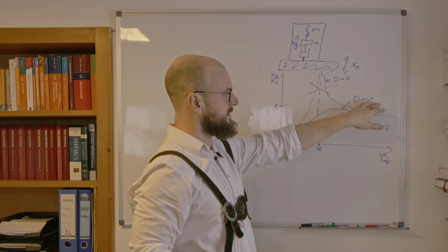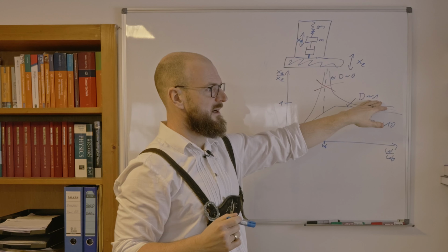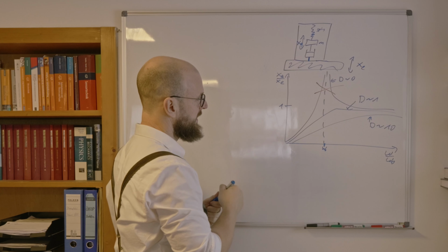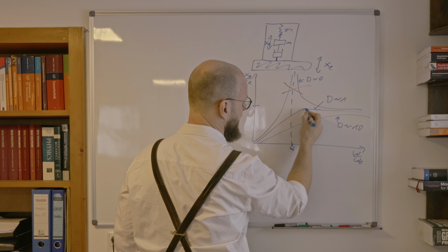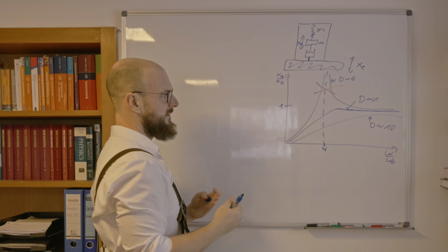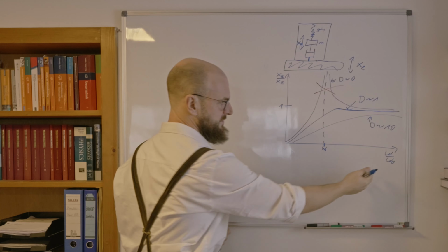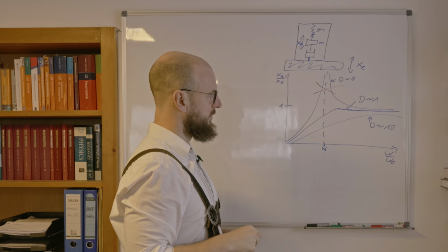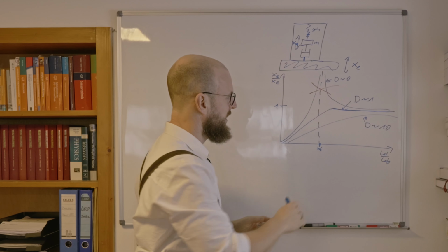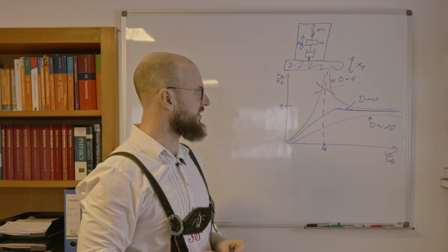That 1 is some ratio between two other values, but it defines a value of damping we can calculate at least, which is at a very specific place, which gives us the most linear behavior at the biggest range of the spectrum over here. And that is the thing we wish to have. We want to have a mostly linear behavior, which this damping case fulfills the best.